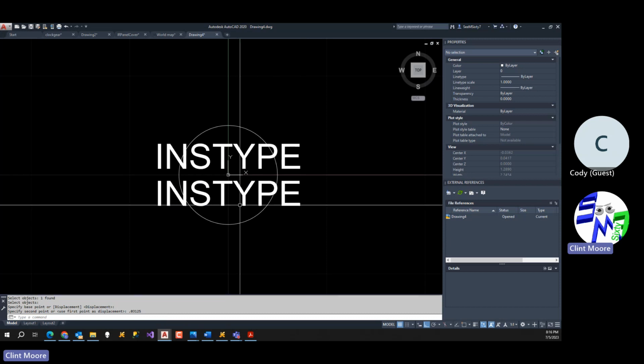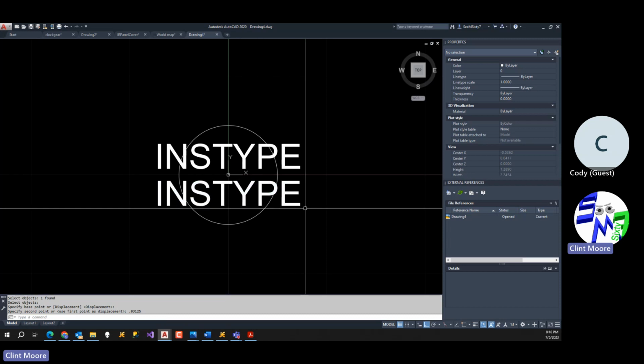Now, something that would make life easier on me is if my snap was actually set up. I take my snap, it's at 1/2 inch. If I turn on snap right now, it's going to be popping half of the bubble. So I want to actually set that to 0.0625, which is a pretty good snap height. So now here I am.